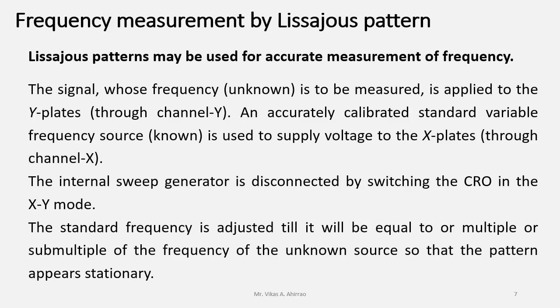After that, the standard frequency is adjusted until it is equal to a multiple or submultiple of the frequency of the unknown source, so that the Lissajous pattern appears to be almost stationary.